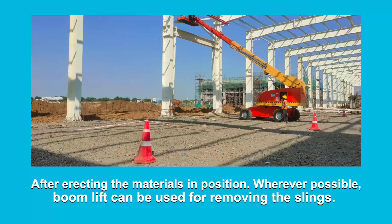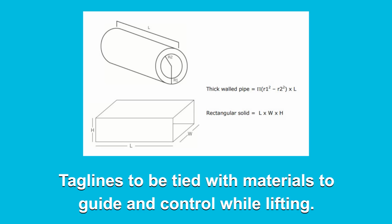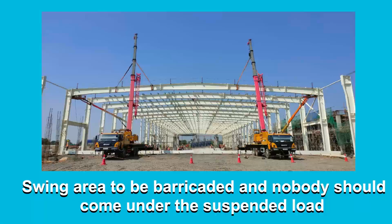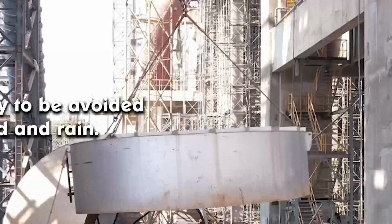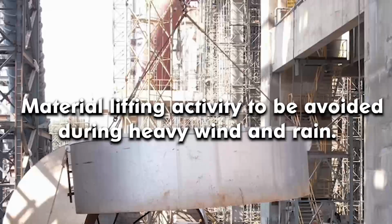Wherever possible, boom lift can be used for removing the slings. We need to provide packings if slings are taken on sharp corners. Taglines to be tied with materials to guide and control while lifting. Swing area to be barricaded and nobody should come under the suspended load. Material lifting activity to be avoided during heavy wind and rain.